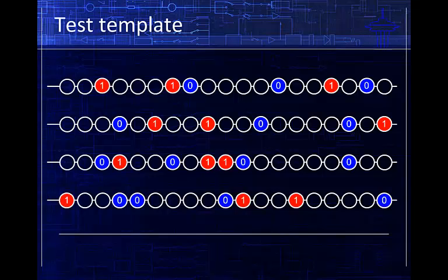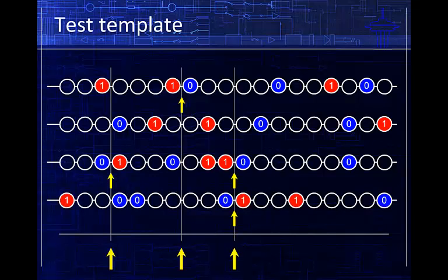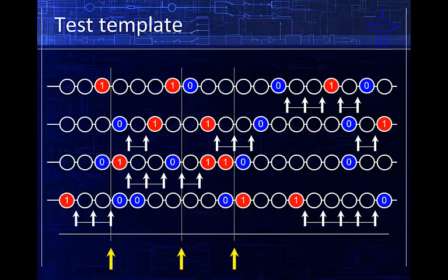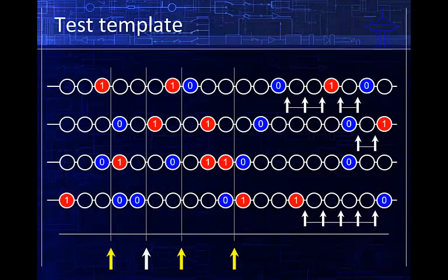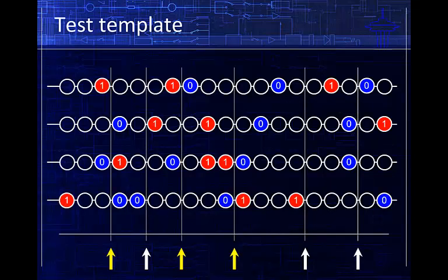The objective here is to maximize the number of residual templates covered by a minimal number of toggle points. We start with the prime toggle points. These are the points between the adjacent scan cells with the opposite values. Therefore, they are necessary. They may also cover some other range. To efficiently cover all the remaining toggle ranges, we use heuristics derived from the minimum cover problem. Here we are showing template generation for 4 residual test cubes.